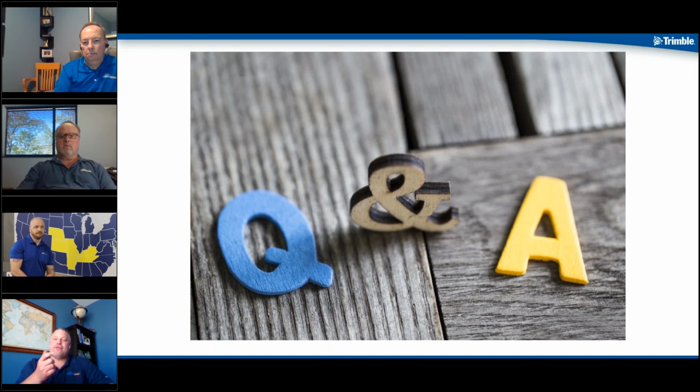So you can flip-flop those around, but just know that before you import data into your tablet, just know the data that you're bringing in. Make sure that data is northing easting, or if it's XY. And before you import that data, make sure you have those settings set up correctly on your tablet to ensure that it comes in the right spot and not everything's mirrored or flipped in the wrong area. So it goes back to challenge where you're getting your data. Ask those questions ahead of time. Is this data XYZ, or is it northing easting elevation?